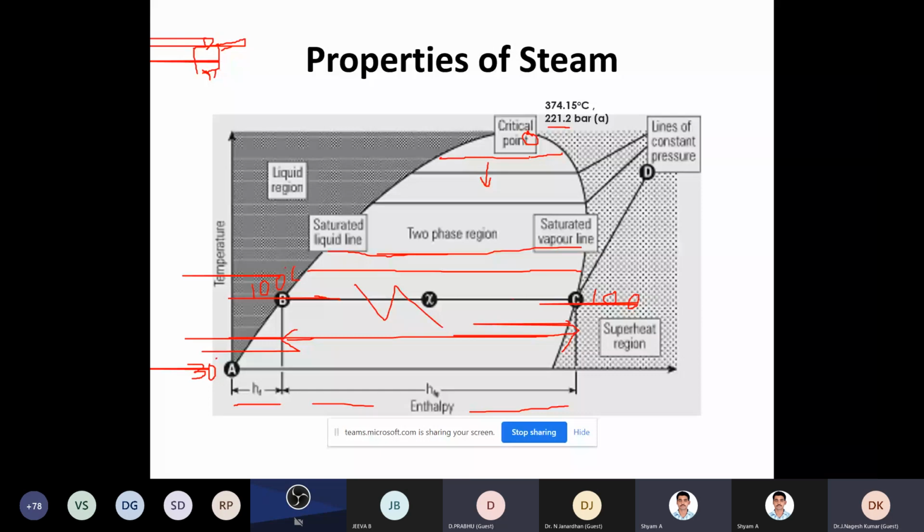So that is why you will find that nowadays the boilers in modern power plants operate at supercritical cycles. That means the pressure involved in the power plants is beyond 221 bar. It may go up to 240 bar also. So there's no latent heat. Directly it goes beyond the critical point and goes into the turbine, generates kinetic energy for power generation.